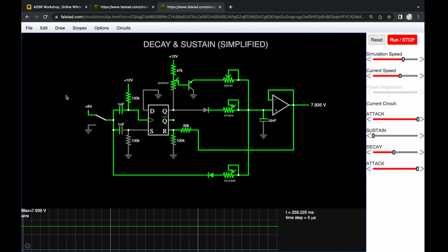And whenever we go above those 3 volts, the comparator would push out a high level voltage, and that would be fine. But then the problem is whenever the comparator switches into the opposite state, so when the input voltage is below the threshold, it will go negative. And this is annoying because we don't want negative 12 volts, but instead we want ground.